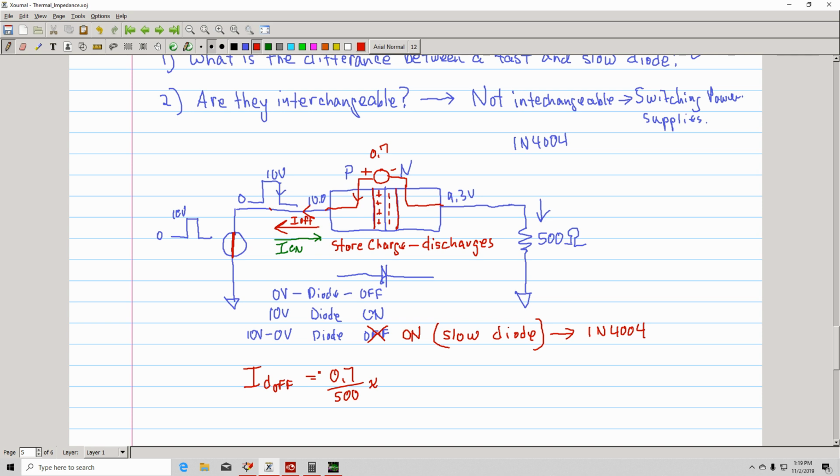And as you go up to faster and higher frequencies, you want to be sure that you're using fast diodes or ultra fast diodes, where you have the trr somewhere in the 70 nanosecond region or faster.